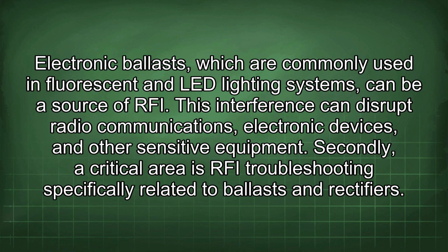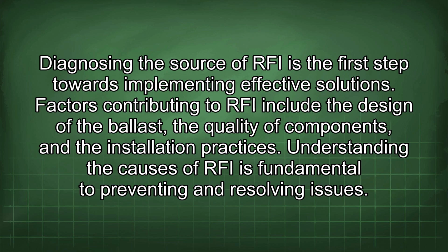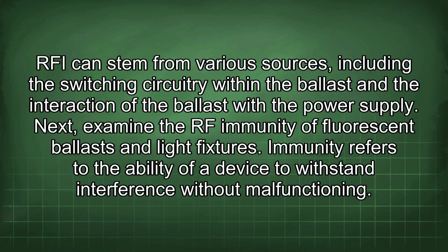Secondly, a critical area is RFI troubleshooting specifically related to ballasts and rectifiers. Diagnosing the source of RFI is the first step towards implementing effective solutions. Factors contributing to RFI include the design of the ballast, the quality of components, and the installation practices. Understanding the causes of RFI is fundamental to preventing and resolving issues. RFI can stem from various sources, including the switching circuitry within the ballast and the interaction of the ballast with the power supply.